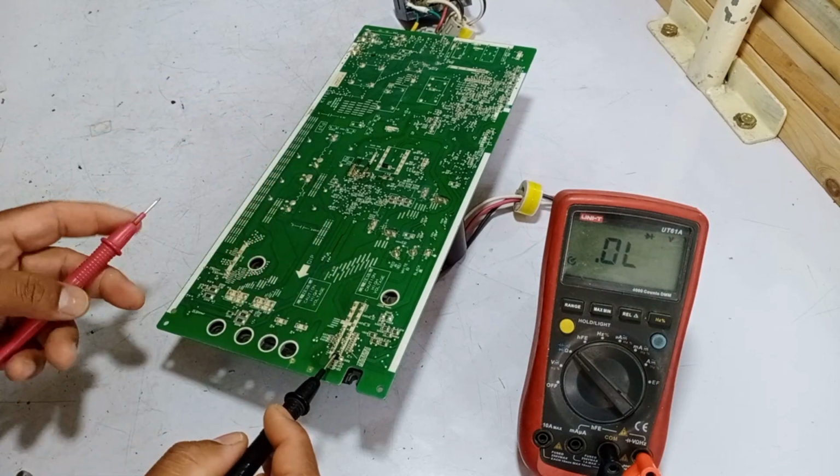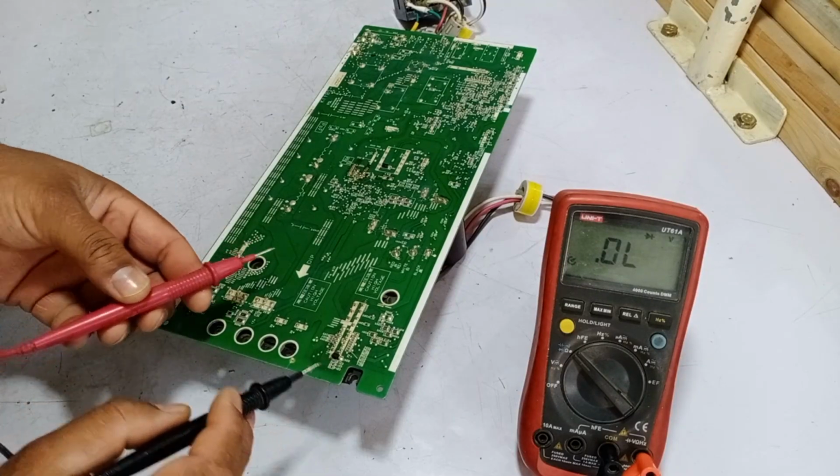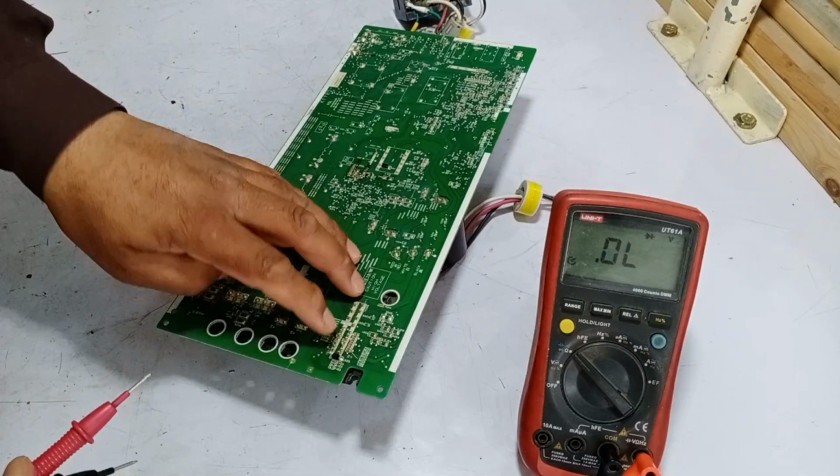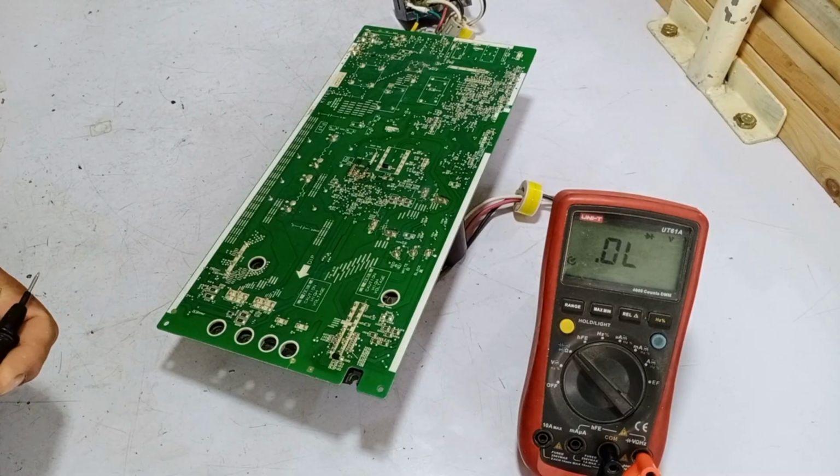To fix this issue, I will: 1. Replace the faulty Zener diode with another 24-volt Zener diode. 2. Once the replacement is complete, the system will function properly, and the continuity issue will also be resolved.